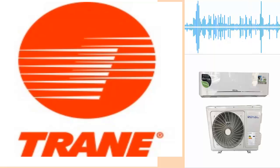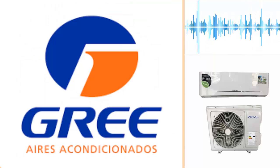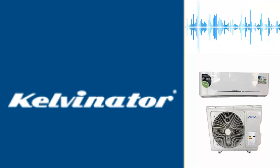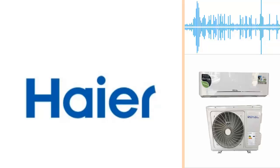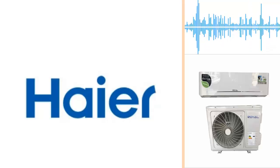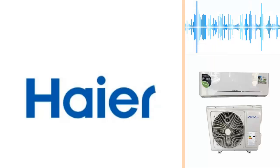Trane, Gree, Sharp, Electrolux, Kelvinator: error E4 means protection against high compressor exhaust temperatures. Hisense, indoor unit: error E4 indicates an incorrect EEPROM. In portable Hisense air conditioners, error E4 means the unit has a built-in tank that needs periodic emptying.